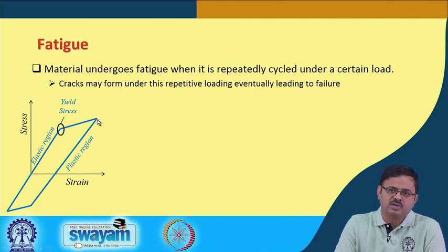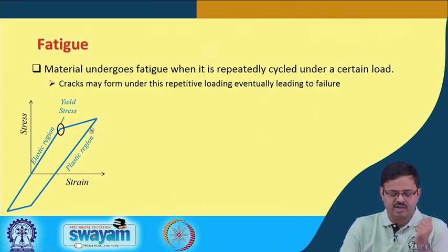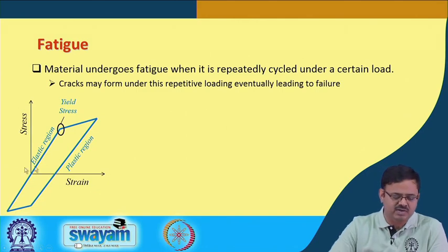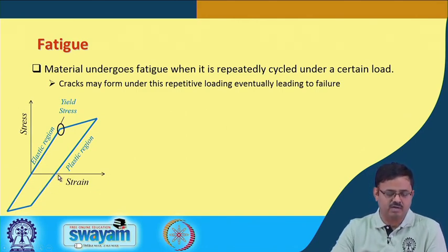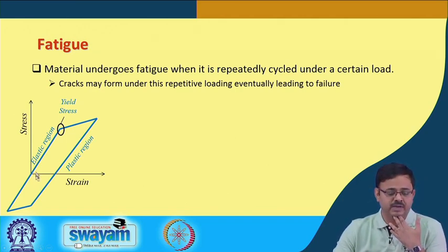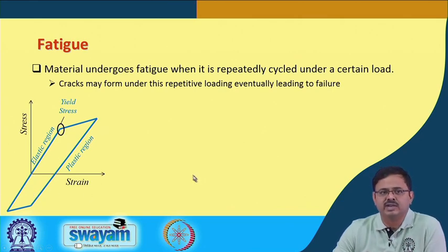So, now if you come to this point and then start withdrawing the stress, withdrawing the load and bring it down, it is not going to come back to the original position. It is going to come back with some residual strain, right. So, this is how it goes. Same thing, if you now apply compressive load, it is going to go down till here, this will be in the elastic region, but again then there will be this plastic deformation, and again as you bring it down, this is how it is going to happen. It may or may not come back to this exact point. I mean, these two have to be exactly equal, but I am trying to illustrate this one, right.